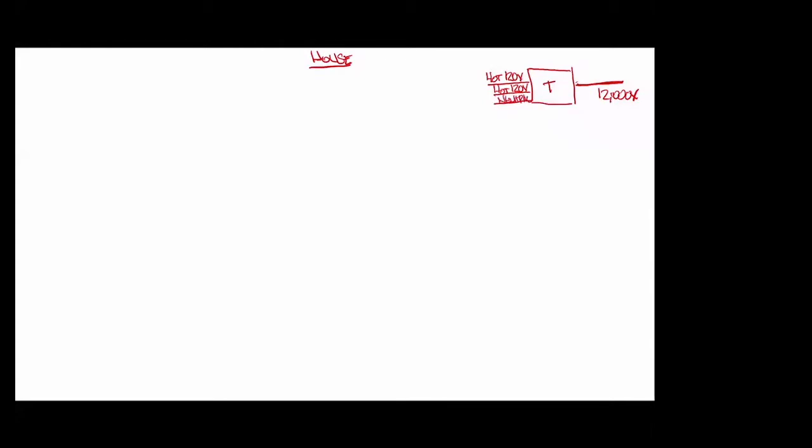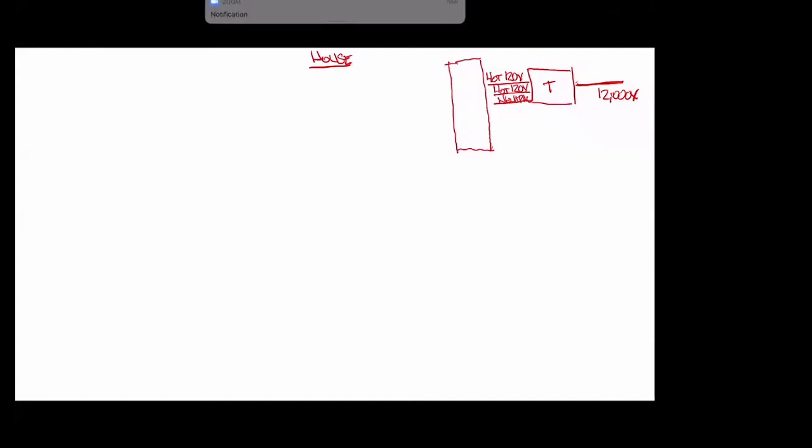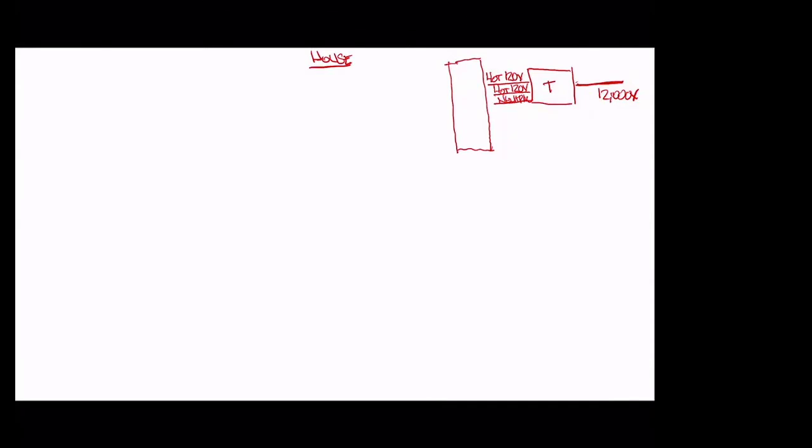Now, these wires are then going to go into a circuit breaker, kind of like what we just drew. And that circuit breaker is not only going to distribute the power to the different branch circuits, telling the electrons, you go over here and you go over there, but it's also going to provide overcurrent protection. So if there is a situation where the wire gets too hot or there's a short circuit, there's going to be a little switch in the circuit breaker that's going to flip off.